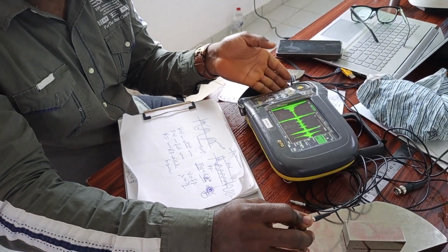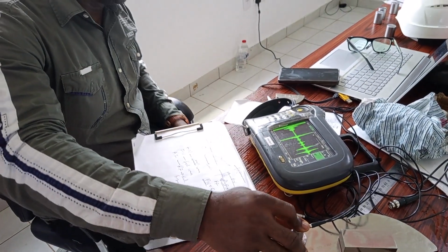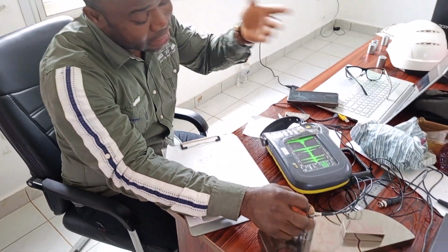So where is it relevant? When do you need to use it? In TOFD, the signals are usually represented in the form of RF. So if you are very comfortable with reading RF signals like this in your conventional UT, it's very easy for you to interpret when you do TOFD. Then there are specific inspections where the owner or the client will request that your signal should be presented in the RF. So you should be able to differentiate and interpret it.